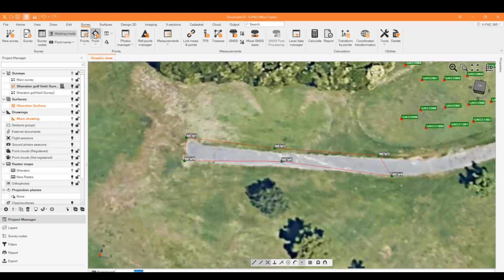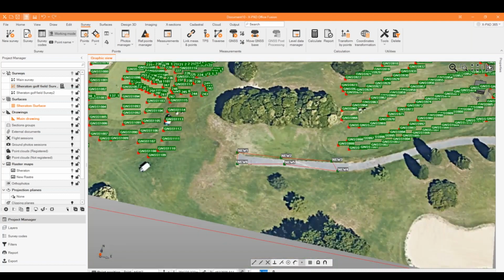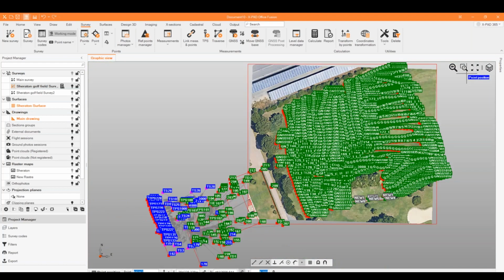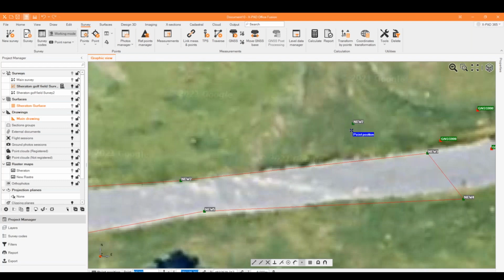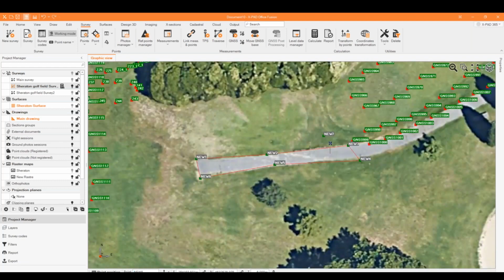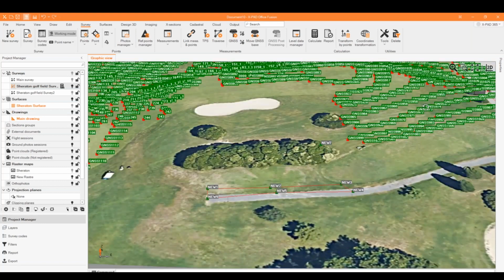If I want to create new points or drawing, I can directly select, for example, point name, select 6 meters, lock the Z, and now, better in 2D, I can easily create the point. So now the point will have a different elevation.